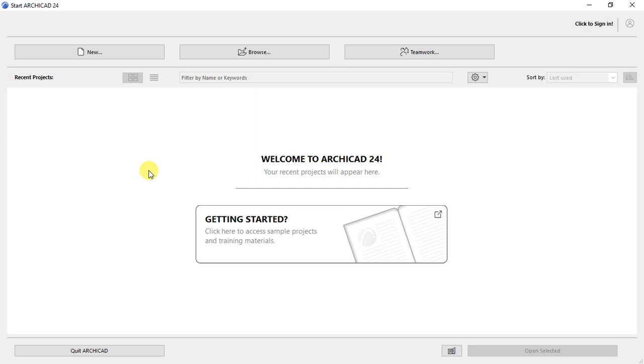And so right now what I want us to do is open an existing project that I have created. Then we will extract data from that project in terms of schedules. In this case we will use interactive wall schedules, and then we will filter that data to only contain the information that we want to use. We will apply some costings based on a cost per square meter, which is a contractor's all-in rate cost, and then at the end of it all we will have achieved our objective of calculating the cost of constructing the walls for this given project.